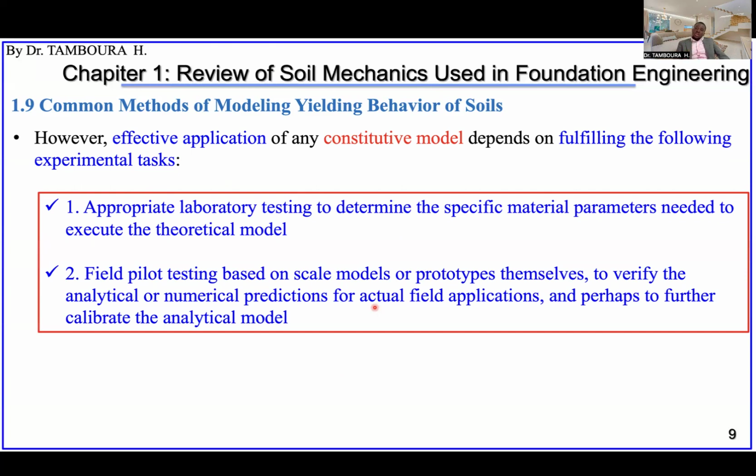That means you go for example, 4 or 5 already built, constructed on the site, on the construction site, the site you want to build nearby. Okay, and you perform loading test on those piles and obtain load settlement curves.